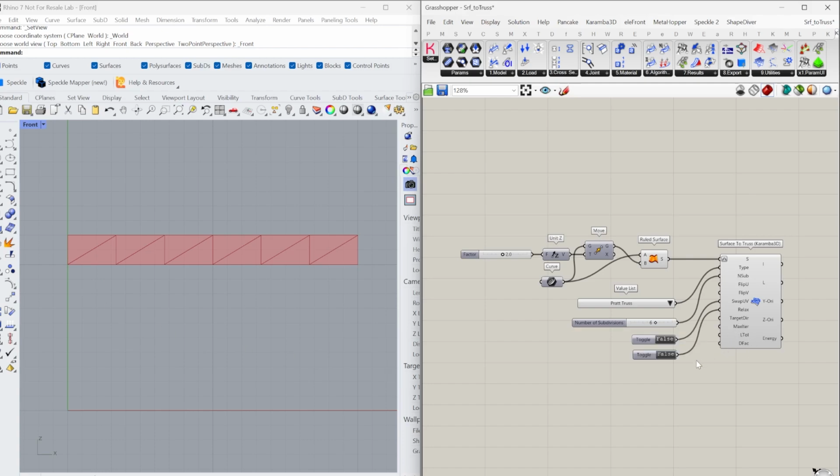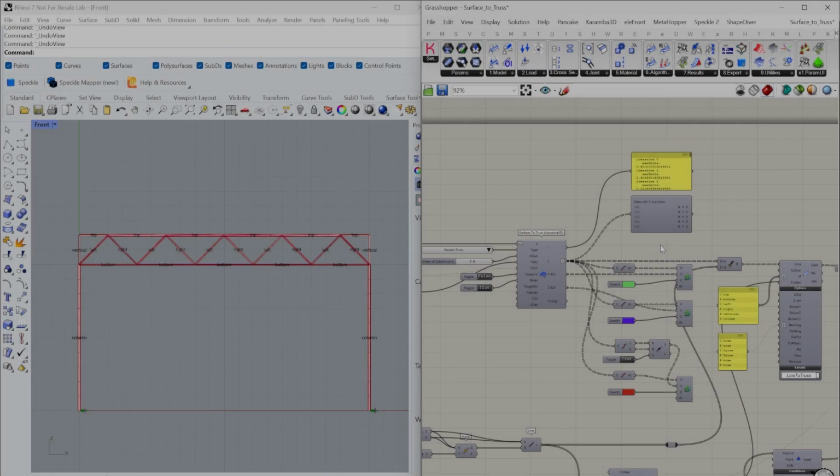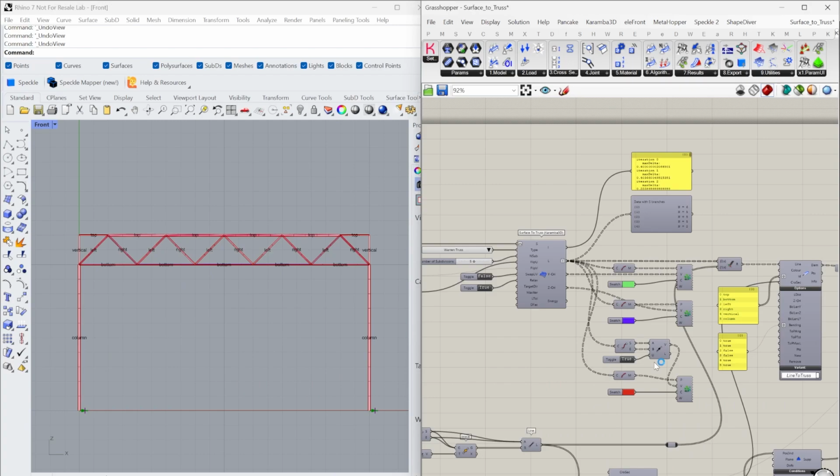The maximum iterations defines the maximum number of steps allowed for the dynamic relaxation of the internal truss angles, while the length tolerance sets a convergence threshold for reaching a stable solution. I also have the damping factor here, which controls the scaling of displacement changes between iterations. These were the inputs, and now let's have a look at the outputs and see how I can apply them.